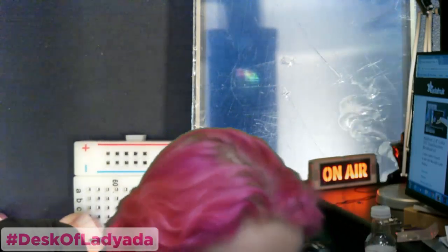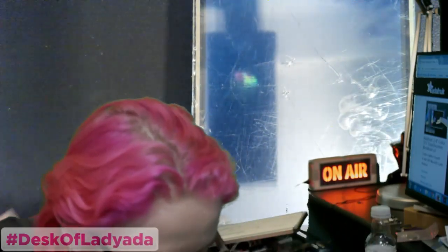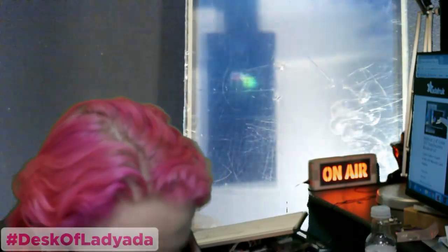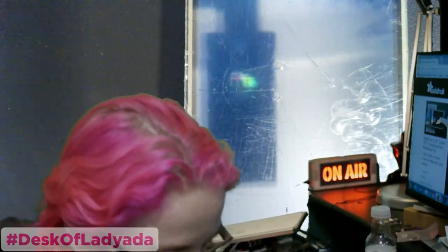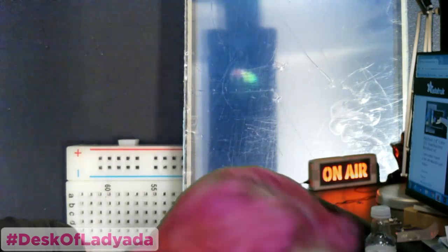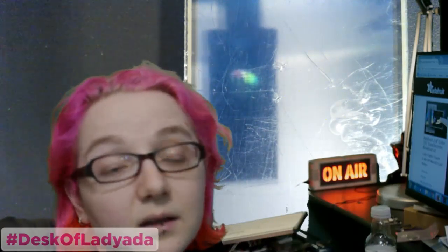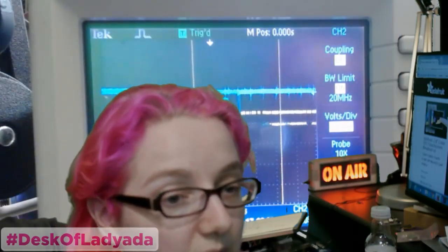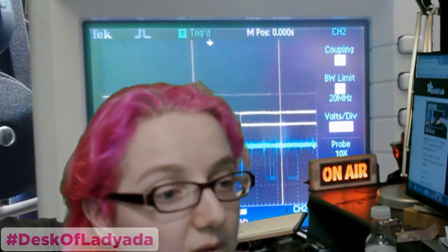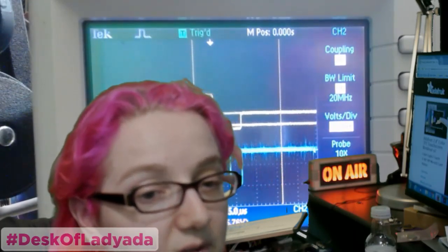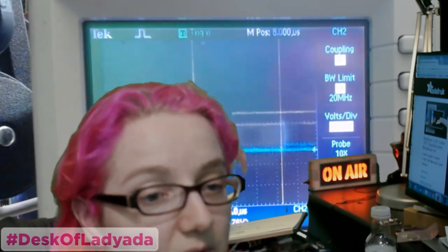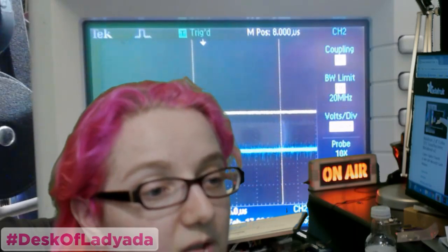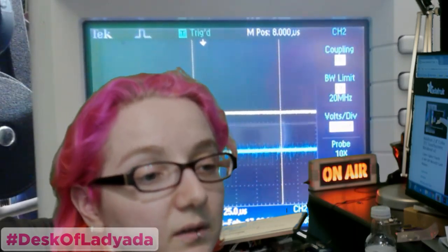All right, so let's hook up X, and then I'm going to also hook up Y. And you'll see that, let's go to the oscilloscope. So you'll see it's a little noisy. Hold on. What am I triggering on? There you go. Someone said you could put the scope in XY mode.